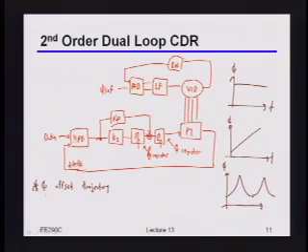It is indeed varying. It turns out in this particular case, it's actually being varied intentionally. Maybe supply? Say that again? Supply? Well, no, okay, you could vary the supply to make this happen, but it turns out that people want things to look like this. They'll actually work really hard to make their PLL on the transmitter side intentionally do this. So, any thoughts as to why you might want to do this? Oh, is this like spread spectrum clocking? There we go. It's spread spectrum.